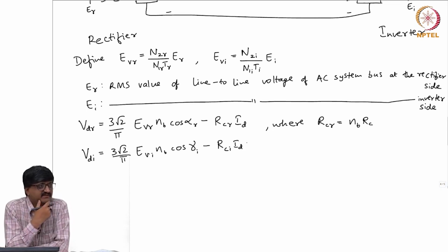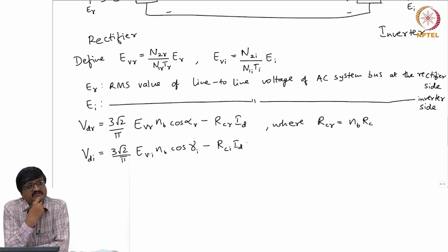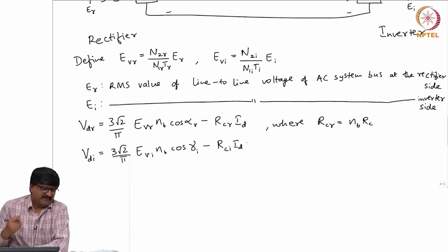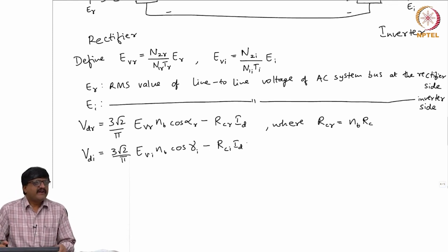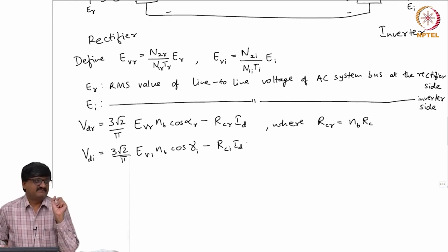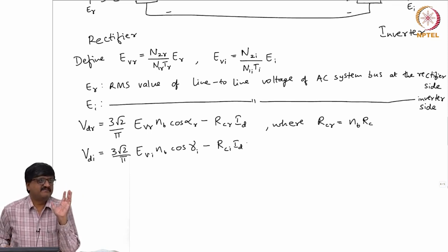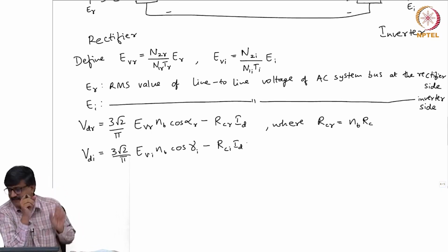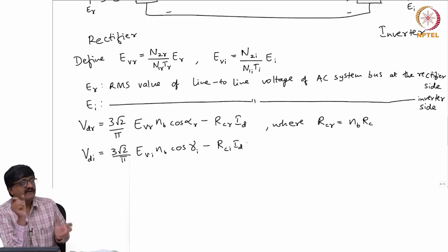Are the two inductances or reactances different? Same, if the transformers are identical. They are the same provided the taps are the same. Please note the taps in general are not the same. The effective inductance that comes into the picture depends on the tap. These are tap changing transformers, and depending on the position of the tap, we have the value of the inductance.